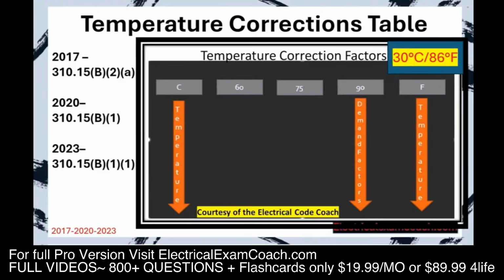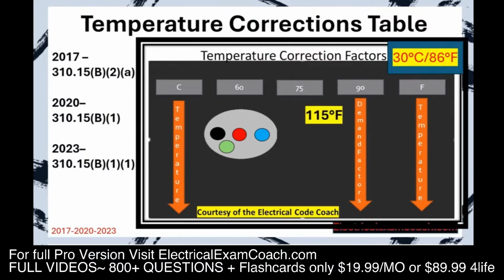Let's imagine that we have this circuit here with our black, red, blue in it, and we have our equipment grounding conductor. Then let's imagine we're in an ambient temperature of 115 degrees Fahrenheit. We would start on the right-hand side and we would find 115 degrees. Then we would come over to the 90 degree C column and we would find our correction factor.